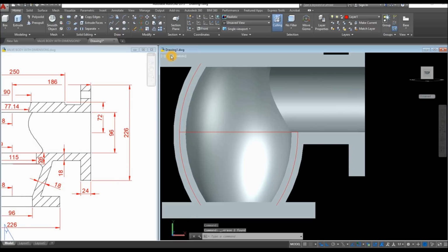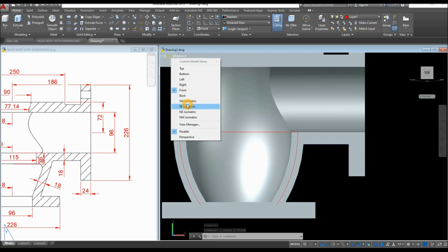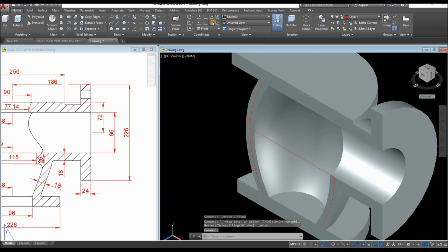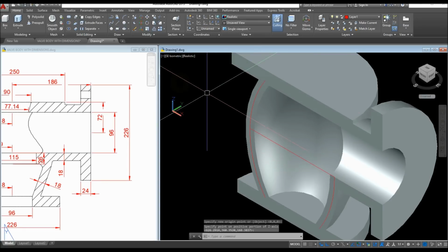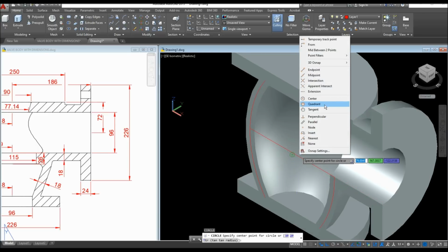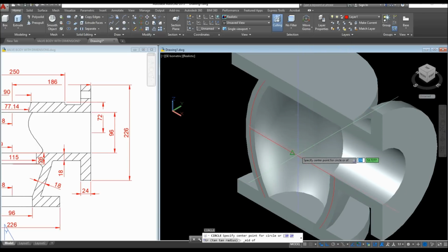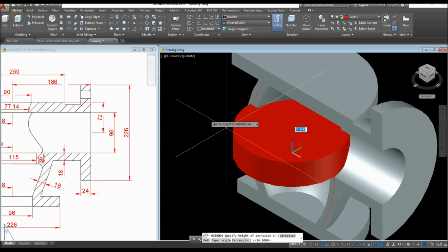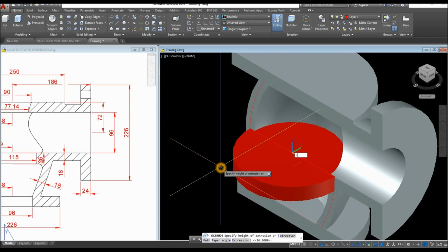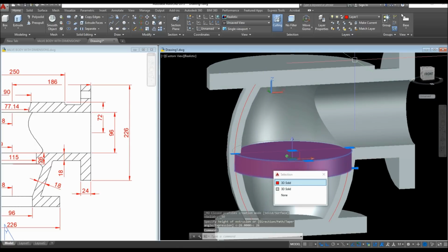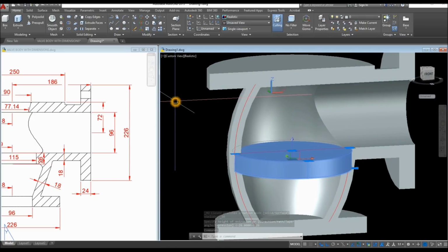Now I'm going to draw a circle. So bring this drawing to southeast isometric, and change the direction of the z-axis vector and point it upward. So circle, snap the midpoint, so shift right click, select midpoint of this line, and snap that endpoint and extrude this one downward for 26 units. And I'm just gonna change the layer for this one to 0 and combine the objects.